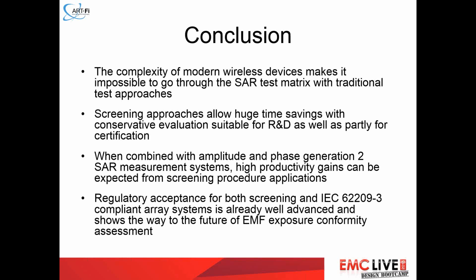You showed 3 procedures for SAR screening. One is basically to test everything and the others simplify the test plan. Are 2 and 3 strictly equivalent? Well, they more or less end up with the same results, but they are not strictly equivalent. For example, the second procedure would be more relevant when you want to test multiple transmission conditions, because you get all the SAR results in a given test position for all the communication systems.